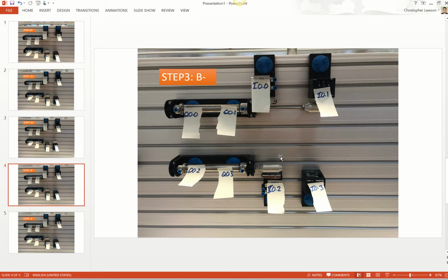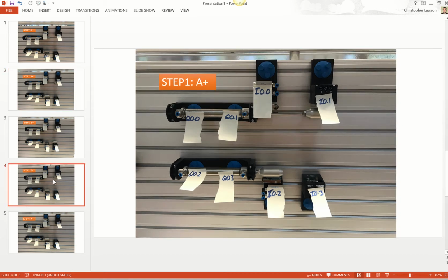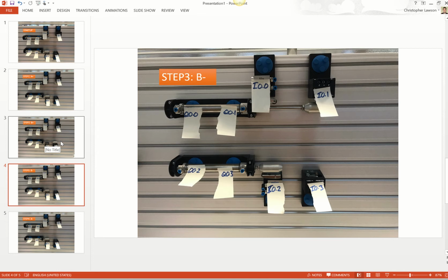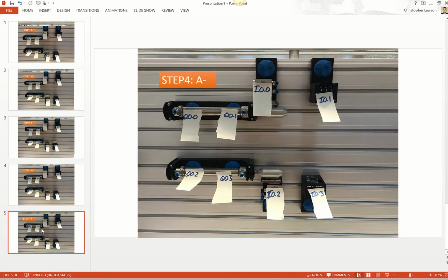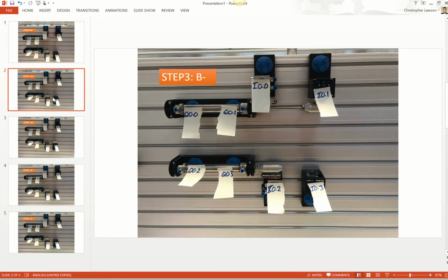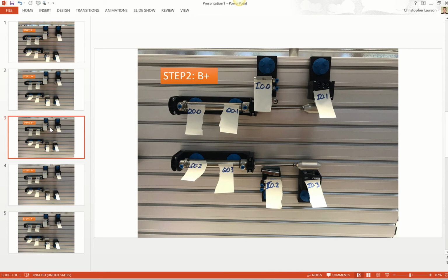So what happens is the PLC gets confused. It doesn't actually know which part of the sequence we're in, and therefore doesn't know which step to go on to, whether it should go on to step 4 or whether we're still on step 1 and we're supposed to be moving on to step 2. And we've no other inputs that can influence the system, and we don't want to buy new inputs because they may be very expensive. So how do we go about that?